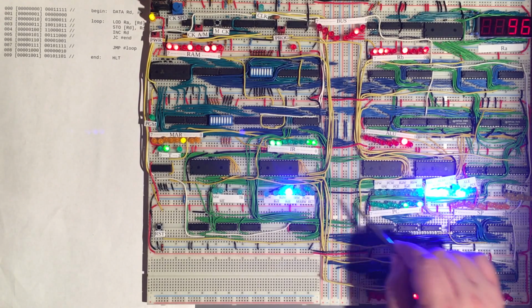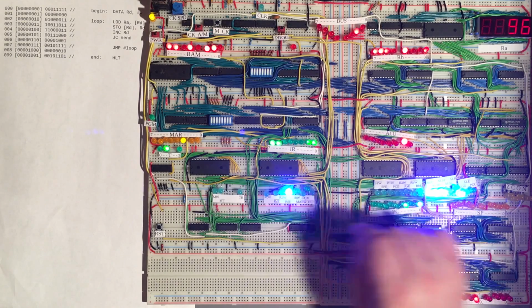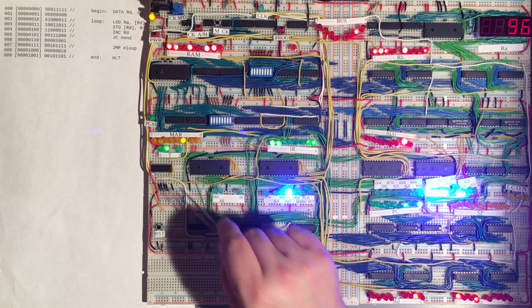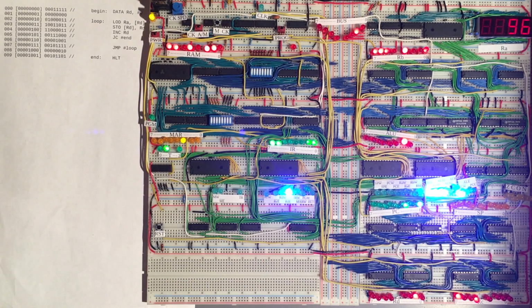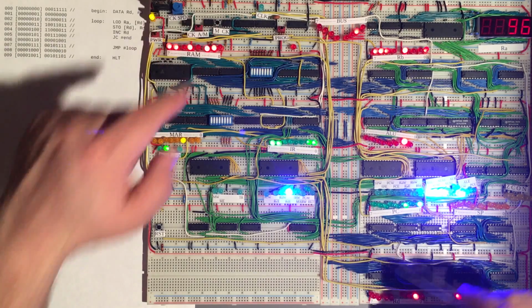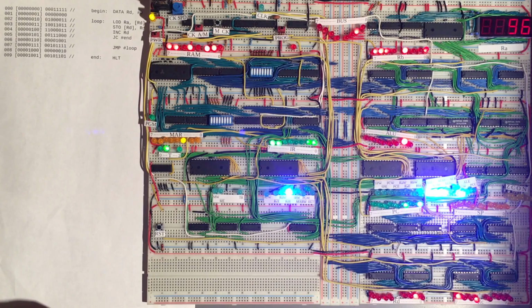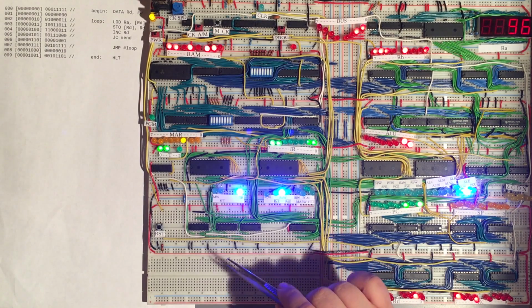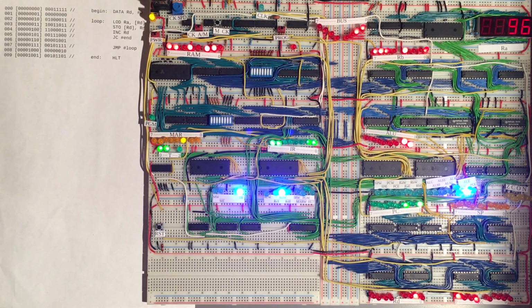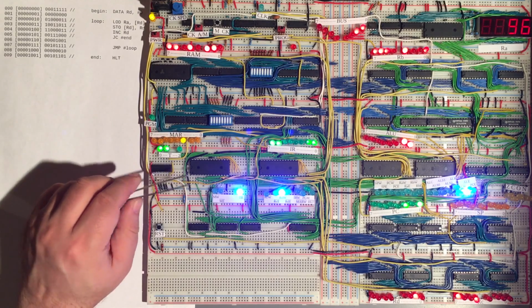And so those are all of the control signals which the microcode needs to assert on the time t2 of this increase instruction. And so when we execute that, this ALU will in fact latch the value of 3. And now that won't carry, so none of these flags will come on. But then here we have the final microcode for the increase instruction.